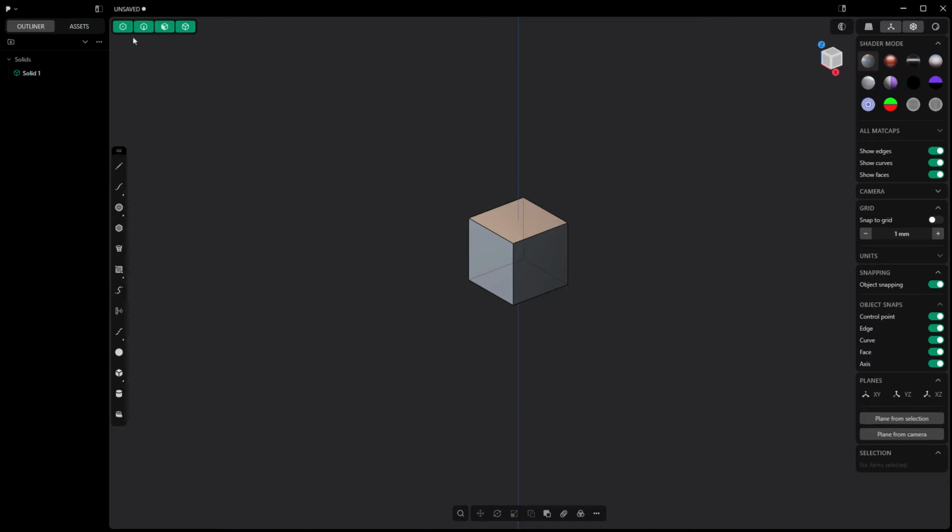The numbers across the top of the keyboard are going to be your selection filter. So 1, 2, 3, 4, and then 5 will reselect all of them. If you hit tab when you don't have any other commands going, that will also reselect all of them for you.